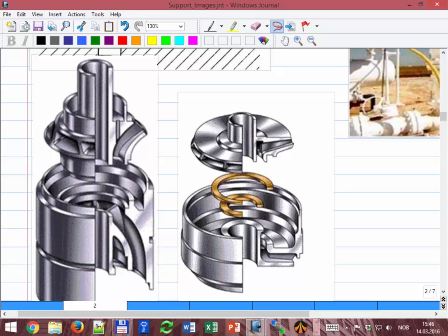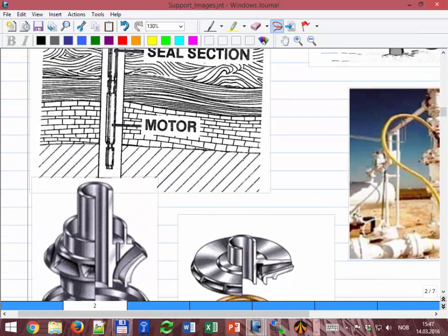And is it 30% also? Yeah, these kind of impellers, they take 30% GVF. These very small ones, like 5%, no more than that. These are made for almost no gas at the intake.